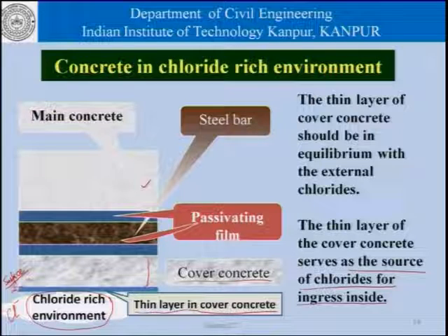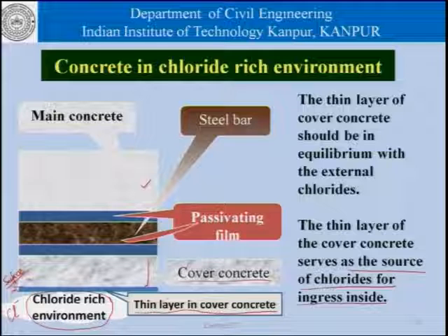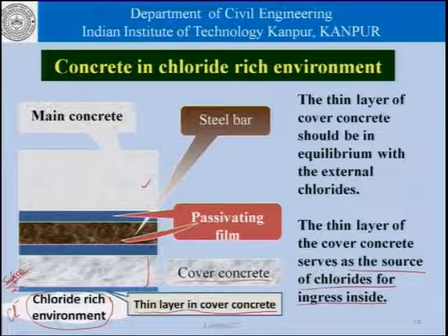So, the way the models are constructed, they assume that the chloride rich environment is in equilibrium with the surface layer of concrete, and that surface layer of concrete serves as the source of chlorides for the penetration of chlorides further into the cover concrete. So, once that distinction is clearly understood, we can proceed further and understand this as a diffusion process.